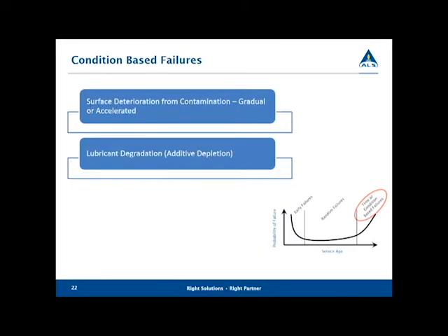Then there's also condition-based failures. That's where we talk about surface deformation, contamination, whether it's gradual or accelerated, and lubricant degradation. Here's where oil analysis really can come into play. Now, I put additive depletion in here, and really, depletion probably isn't the best explanation.